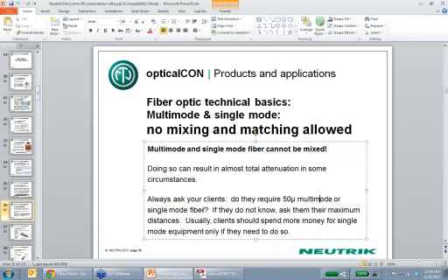So just a quick follow-up from that. He said the question's coming from a video person who hates to run into multimode on job sites. Right. Well, the video people are always single mode, and they've got good reason to be. The mixed AV people are typically multimode. They've got good reason to be, and it's a problem. Probably over time, multimode will fade out, and we will migrate to single mode. This is the expectation. But when I say over time, this is a long sunset, 10 or 15 years or something until the default idea is single mode.